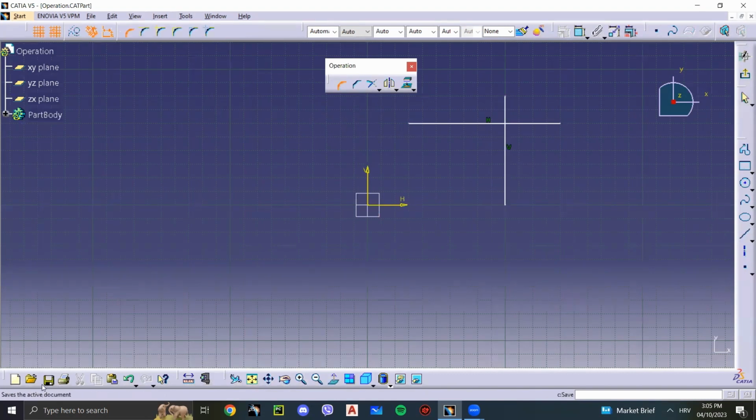So let's put this back here. At the bottom left corner, it says select the first curve or command point. Let's select this line. Let's select the second one. Select this one. And now we have the option to say what radius we want. Let's say 40. And we got 40. You can see how it went in this direction. That's because my mouse went up there.